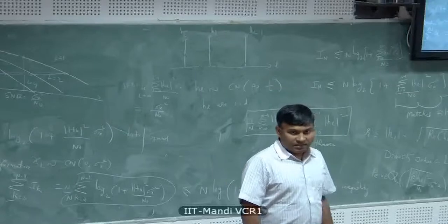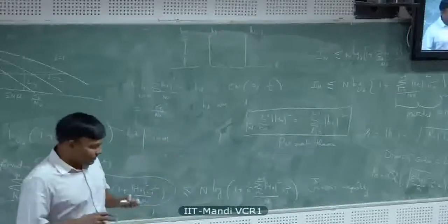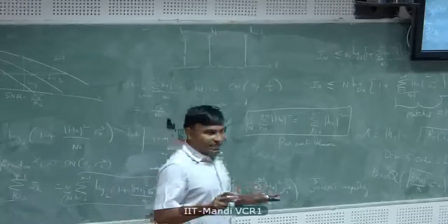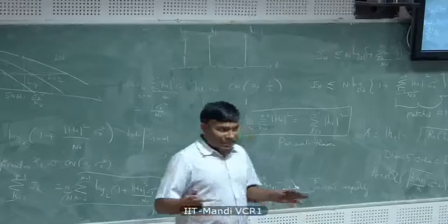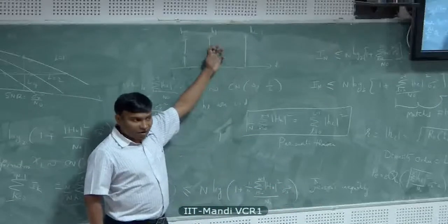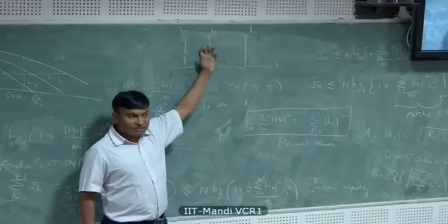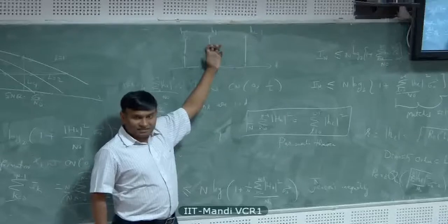Okay, is the notion of diversity clear now? Yeah. So I think the bottom line is you have to understand the wireless channel. The whole magic is in the wireless channel. How many taps do you have as a function of bandwidth? If you have 30 kilohertz, how many taps do you have? If you have 5 megahertz, how many taps do you have?